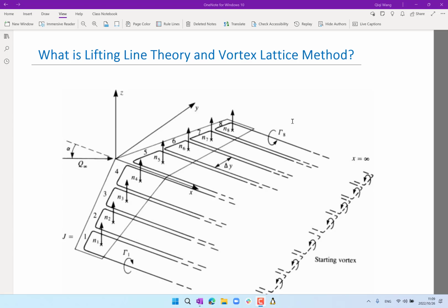And then we can wrap this whole thing into an optimization routine and optimize not just for the minimum induced drag, but also take into consideration stability, right? What is the rigidity of the wing? If you have different span-wise loading, as we're probably going to do in the project section, you're going to have a different estimate of how strong the wing has to be, and therefore how much the wing has to weigh.